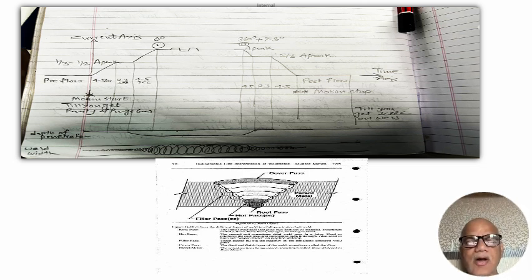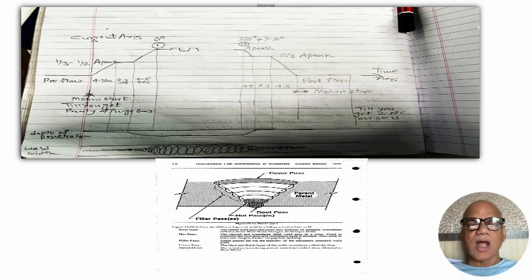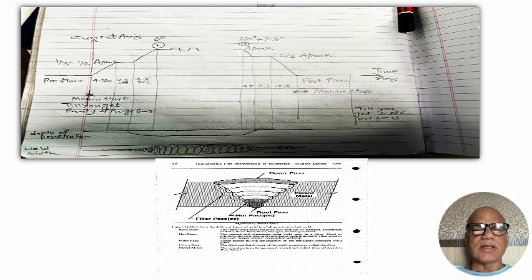So a little study of the joint, making sure that for every run you have already pre-programmed the machine if programmability is available, or you can select the right knob positions. You can make a chart for each of these passes, what is the setting in each of those knobs you want to keep, and then hand over that sheet to the welder and ensure that he follows it.